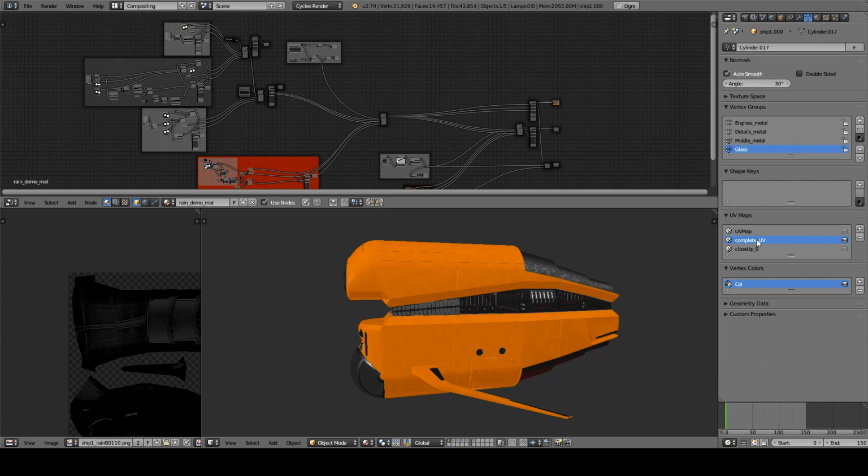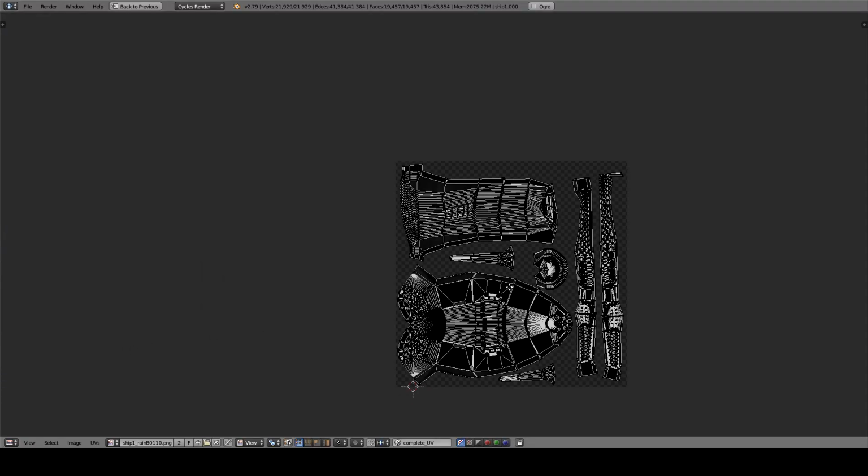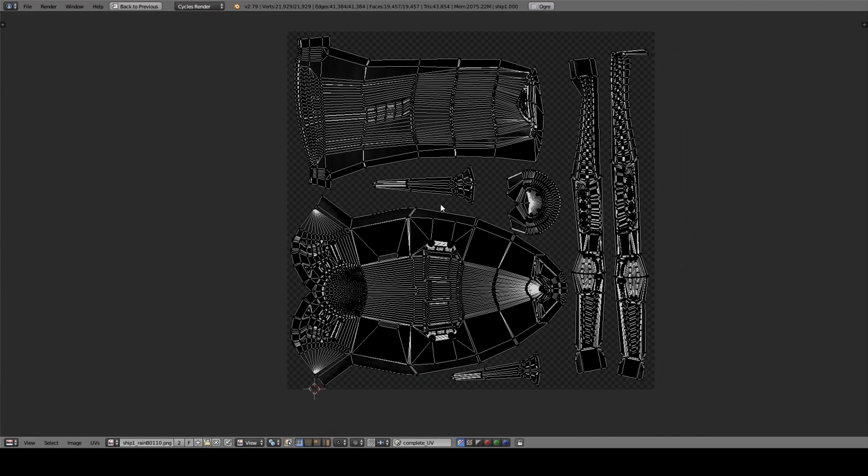First, you should probably have a set of UVs dedicated to baking. Then, make sure that your UVs don't have too many disjoint surfaces, because the dynamic paint algorithm is going to crash otherwise. You wouldn't want your rain simulation to overflow, would you?